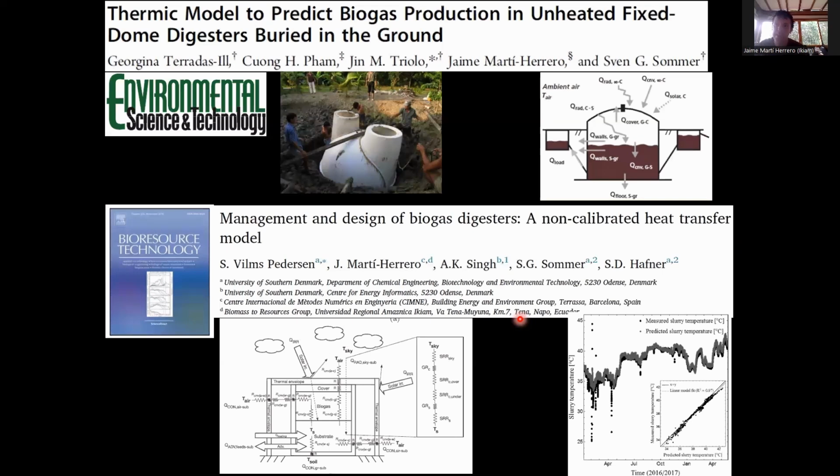And what we found at the end is that we can put the digester at the same temperature as the maximum ambient temperature that you have in a place. So I don't know what the case is in London, or in Leeds or in Oxford, but if the maximum temperature during the winter is, I don't know, 15 degrees or 12 degrees, you can achieve this temperature inside the digester if you consider the insulation, the greenhouse, and the black color for the reactor.